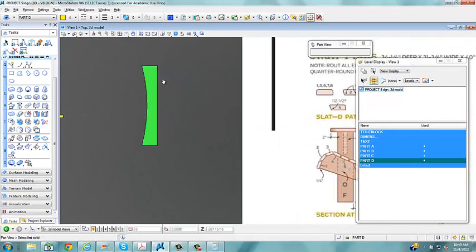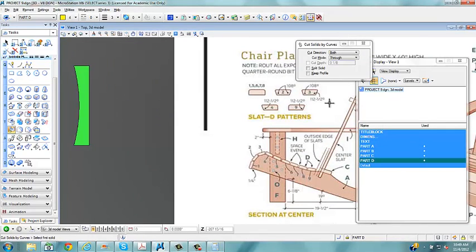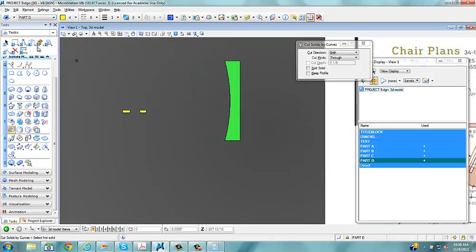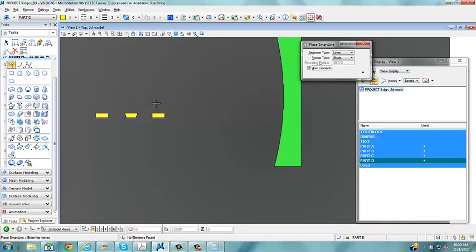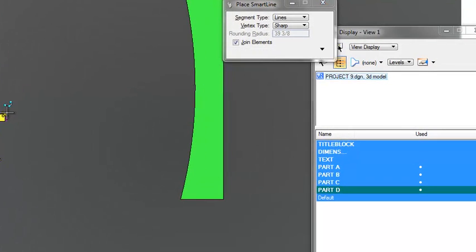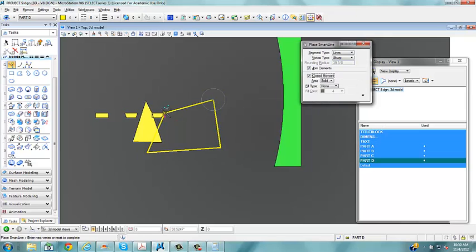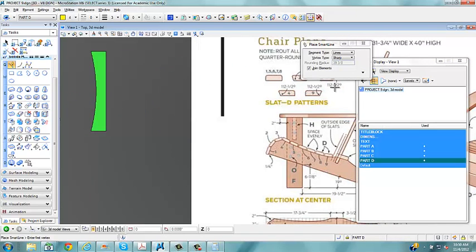That's going to be for number 2, number 3. They're both 108. Oh, one's 108 and the other one's 112.5 degrees. Well, it's kind of special. Anyway, we'll take this one and copy it. This time I'll say join elements. So we're going to say 108. This one will be minus 112.5. Let's just check that. 112.5.